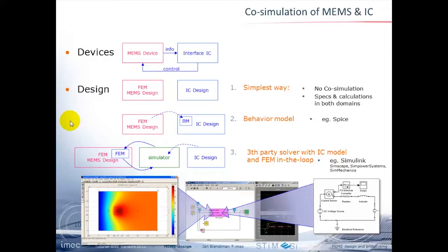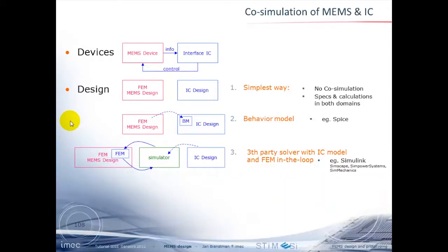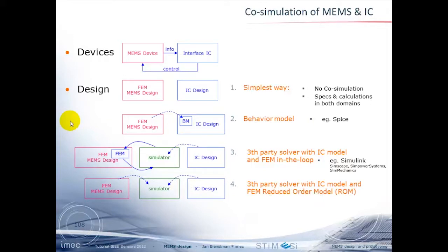So this is the model in COMSOL, and it is an S function in Simulink, and Simulink, Simscape, now SimPower Mechanics, they offer also some electrical components. Or you have extra plugins that you can really import your SPICE into Simulink, but these are third-party softwares. And that allows you to do the co-simulation. And every iteration here, it does the simulation over the FEM domain in the loop, which is a restriction. So for simple geometries, and in this case a temperature model, for example, to just model heat control over structure, it can be done. But it's not a good solution for very large geometries, because the speed of the simulation is enormously reduced by going over the loop of the finite element domain for complex geometry. One solution was to go for a reduced order model.